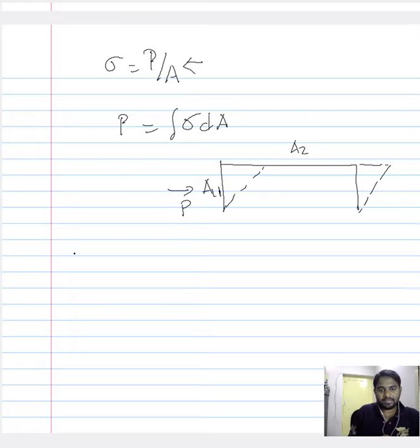In our earlier description, we saw that stress is dependent on cross-section area. So if you consider the same definition for the shear stress as well, and denote shear stress as such, the expression for the shear stress would be P by A1. If you consider a system similar to tensile loading, wherein the stress is defined as the ratio of the load and the cross-sectional area, and adapt a similar definition for the shear loading, then the expression would be load per area A1.